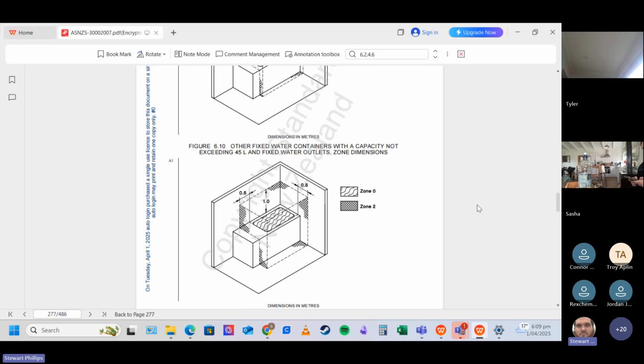So, for example, my house, I have an internal garage on the ground floor, and that's where our switchboard is, also where the solar battery is. But that's because that's where it was originally put. It's also the closest point. Well, it's not the closest point to supply, but it's out of the way. A lot of modern homes are built with the switchboard either in the stairwell, hallway, or in the garage. It's not too often now that you'll see a combination meter switchboard installed new outside. I've only ever done those as retrofit.